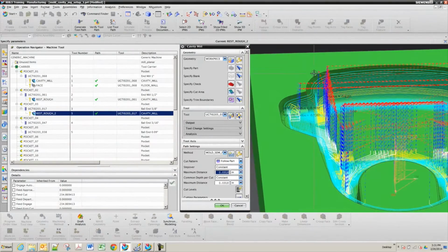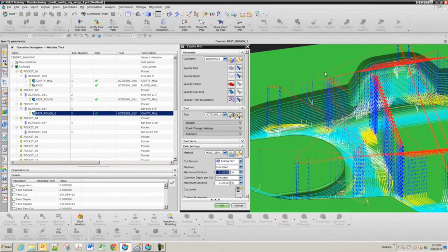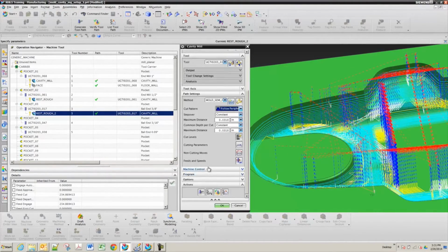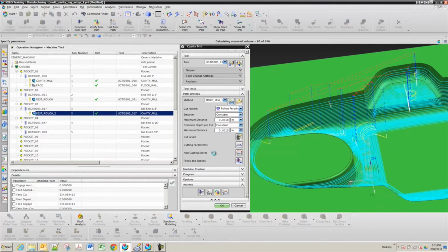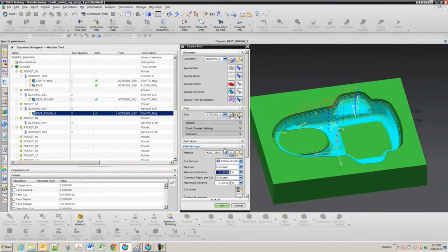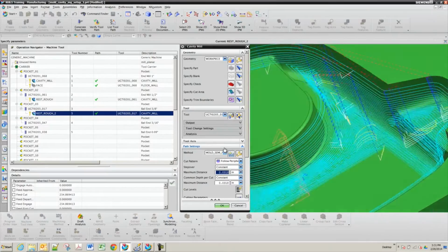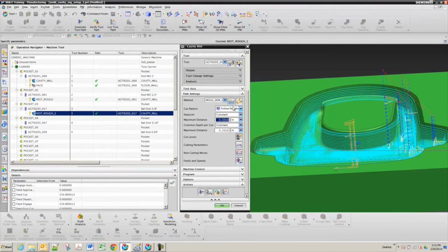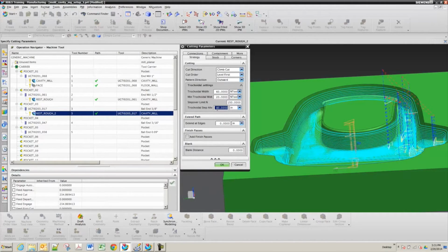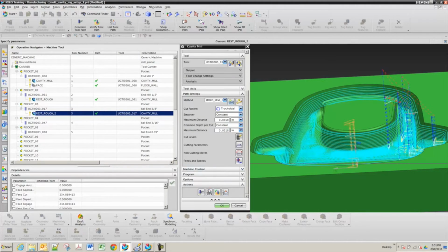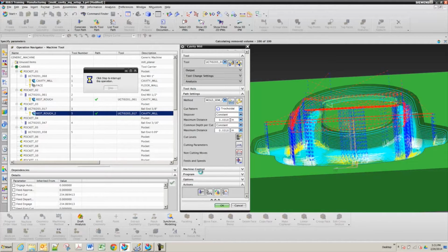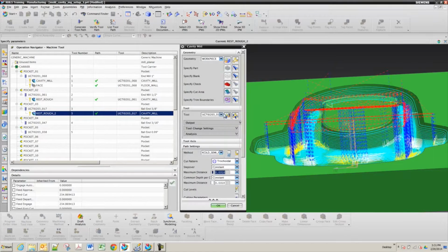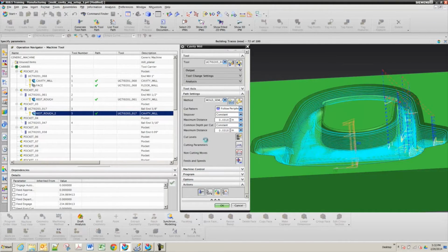Yeah, mine looks a little busier too. Yeah, that made it jump around, but that's because it's trying to skip most areas. So we could try a different pattern. Yeah, it looks like follow periphery is a better pattern on this one. I would probably use trochoidal, but I always use trochoidal. But it's also crazy looking. So maybe I won't on this one. Yeah, the periphery looks good.